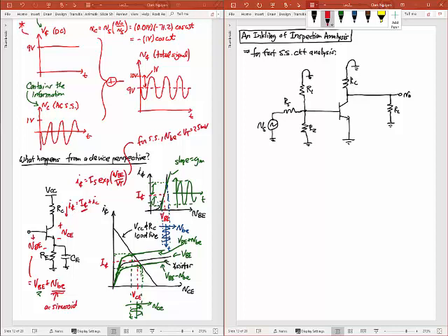You'll look at this transistor, and when you look at this transistor, what are you going to see? You should be able to see the small signal model right on this transistor. Because looking into this thing, I really have an R-pi resistance right there. Right? And I know that my VBE is right across that R-pi resistor. Looking across the collector to emitter of this thing, what do I see?